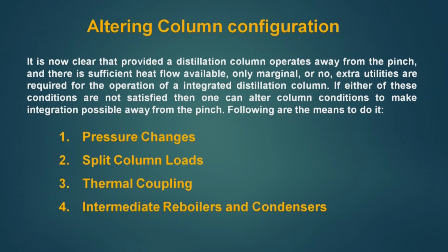We have seen very clearly that for the upper pinch area, if it is integrated, it almost runs free of cost or with marginal increase in the utility. If either of these conditions is not satisfied, then one can alter the column condition to make integration possible away from the pinch.